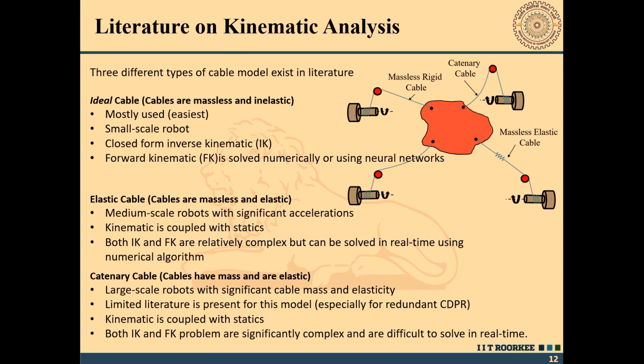And the catenary cable model, where the cable has mass and is also elastic. This is the most generalized, but again we have challenges here. The first case is mostly used, and it is the easiest because we assume that the cables are massless and inelastic.